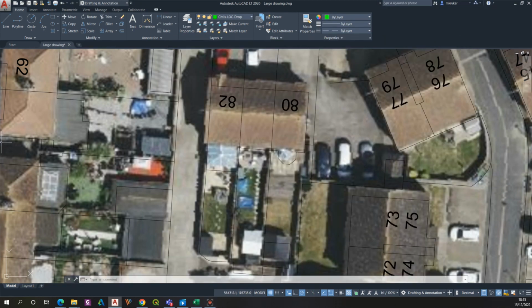All right. There's also another approach which should be considered for finding a place in AutoCAD LT by coordinates. Namely, you can use the circle feature in the draw section, and by selecting even the very first example, you have the option of specifying the center point in your command. So here's the place where you can paste your coordinates and hit enter, and then you see what has happened.